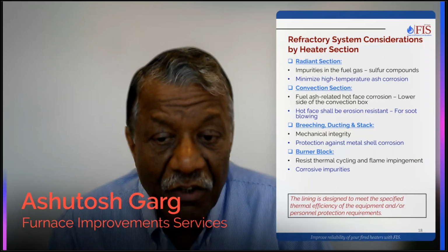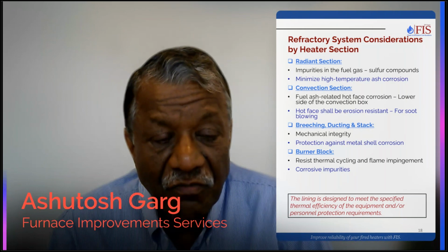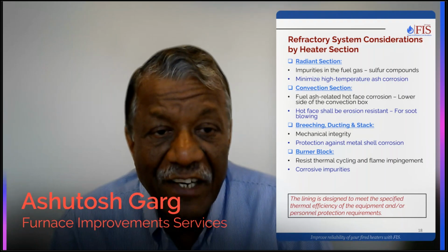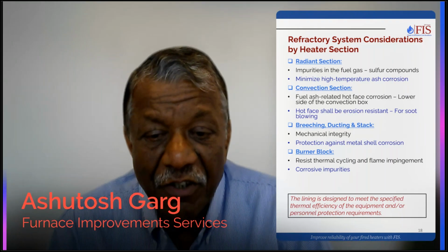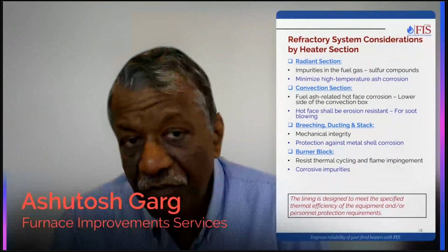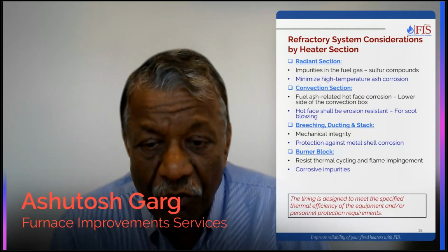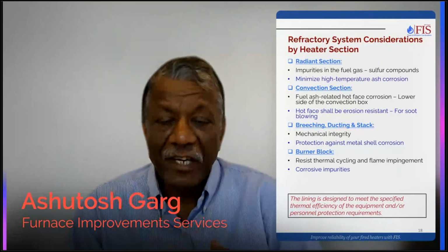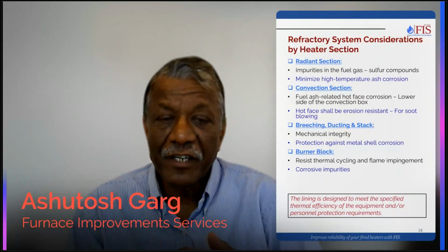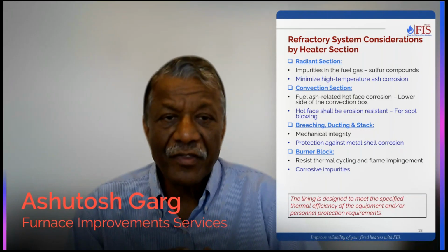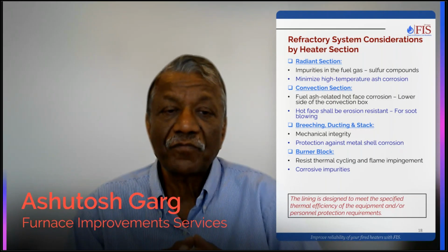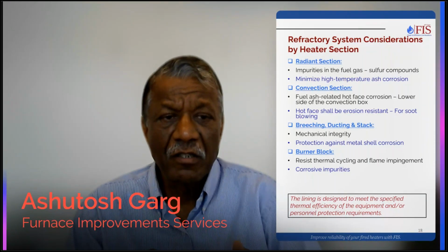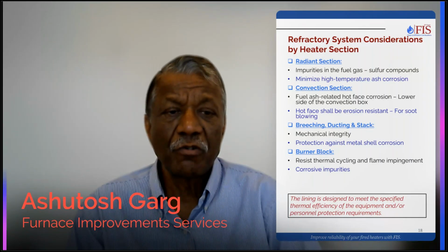So they not only attack high temperature components like intermediate tube sheets and tube supports, but they also attack refractory. So that is one good news when we talk about refractory systems these days, because the fuel is much, much better. We're talking of fuel gas firing. Even in fuel gas firing, they have limited the H2S content to 160 ppm. So things have become much, much easier. You are not worried about ash corrosion. You are not worried about sulfur, vanadium, sodium, etc.